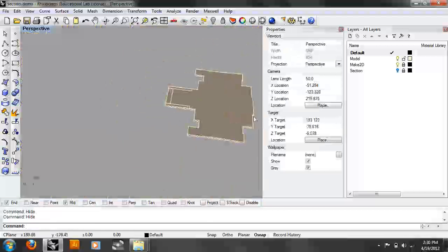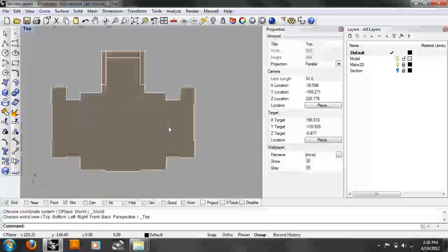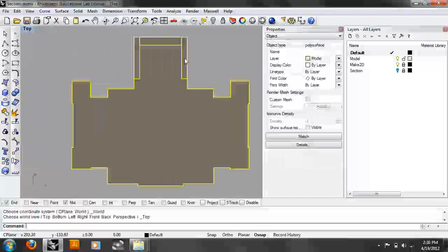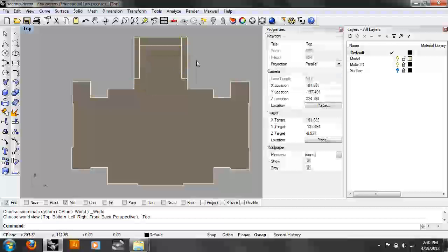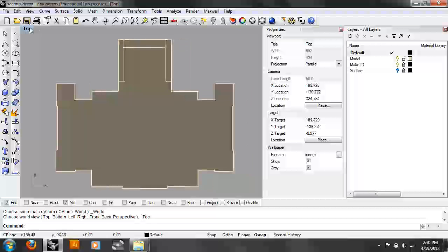So I've got this, and I'm just playing with that. Then I would take the edge of this and add these outlines to it, or you could just trace it with the line tool, and then I'd re-extrude it, and then I would erase these. I can't just Boolean these things together, and that won't get rid of the lines. That'll just basically group them. Booleans aren't that smart, but you are. So yeah, that's how you clean it up.